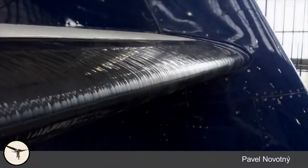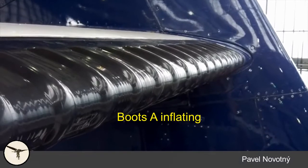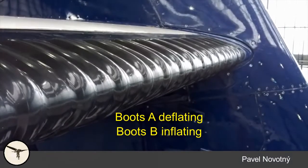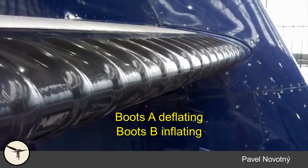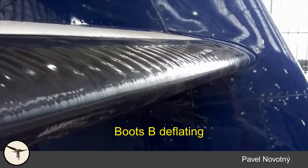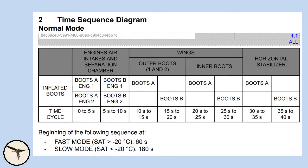Each section is inflated for 5 seconds. This video shows how the boots on the horizontal stabilizer work. The timing sequence varies between ATR variants as they have different numbers of boots on the wings. This figure shows the sequence for the 72-500 and 600.